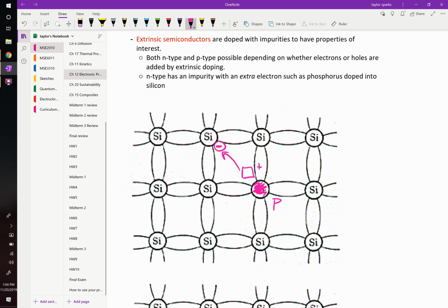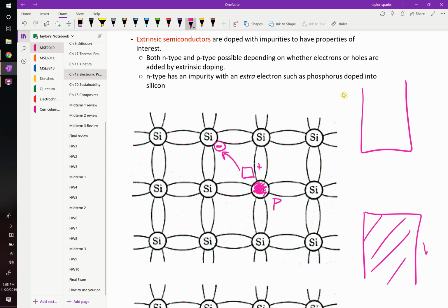You guys follow me? What does this look like in terms of an energy diagram? It looks like this. We've got our valence band down here. And if it was pure silicon, then this is completely filled. The Fermi level is somewhere in the middle. Remember, the Fermi level is at 0 Kelvin. The electrons would fill up to some point, somewhere in the middle, so they fill up to here, and that thing is totally empty. For an intrinsic semiconductor, the way that we get conduction is by promoting things across this big energy penalty to sit up here.